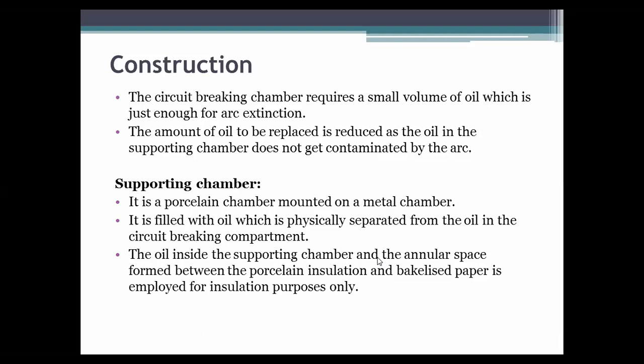Okay, so whatever be the oil inside that supporting chamber, and that space between the porcelain insulation and bakelite paper is employed for the insulation purpose only, means this oil is not used for the arc extinction, that is used for the insulation purpose only.